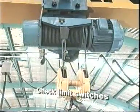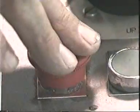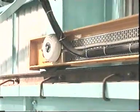Check the operation of all motion limit switches or cutouts. If a limit switch fails, then apply the brake and throw the main switch to off. Also check the operation of audible warning devices, such as the bell.